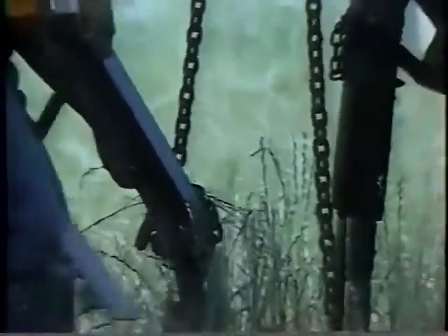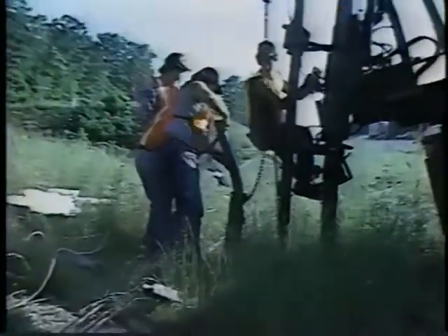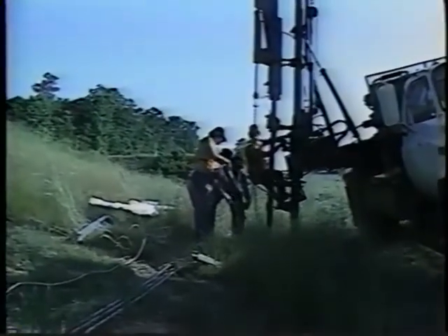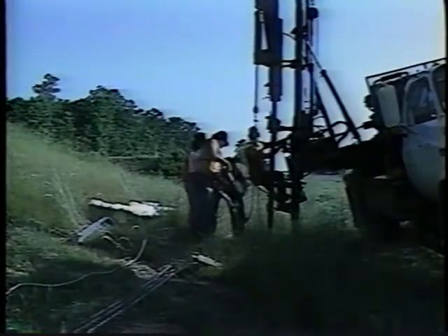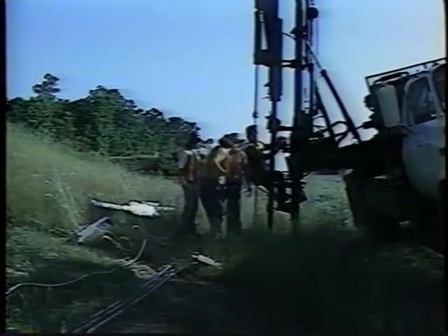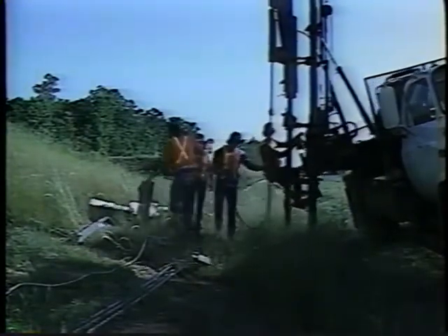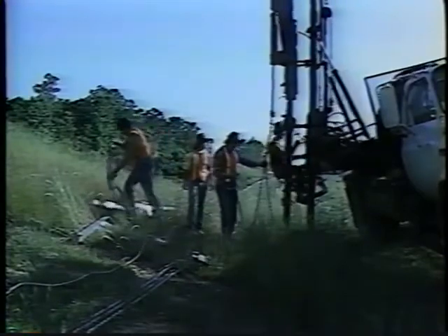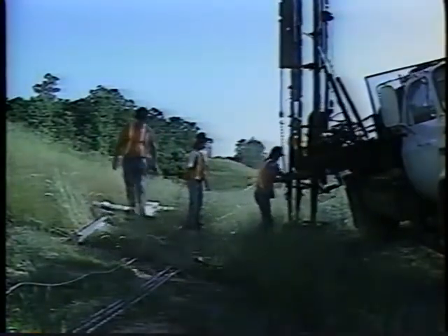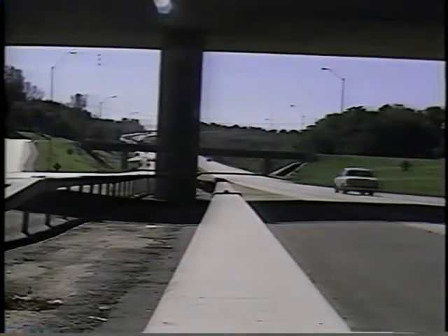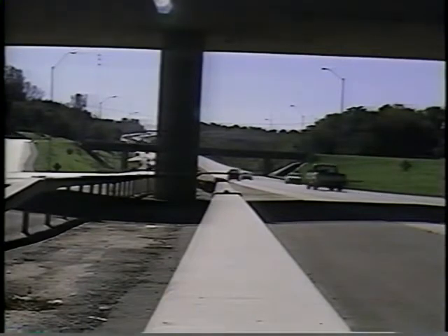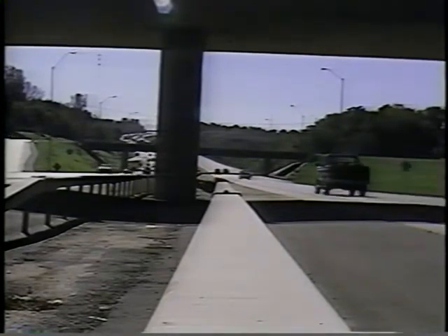But unlike the more rigid systems, flexible barriers receive more permanent damage with each impact and cannot sustain repeated hits without immediate repair. The trade-off is to use flexible systems where they can be set away from the roadway and not be hit so often. Semi-flexible and rigid barriers, which are less susceptible to damage, can be placed closer to the roadway. This strategy balances safety and maintenance costs.